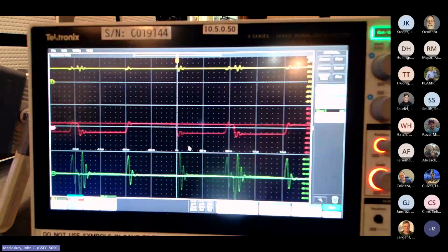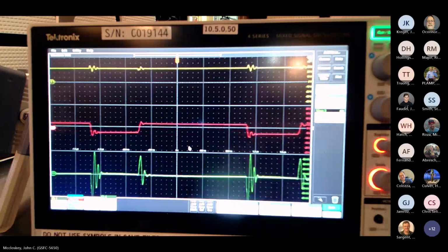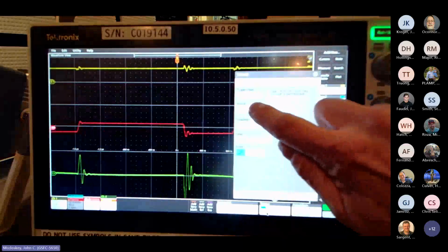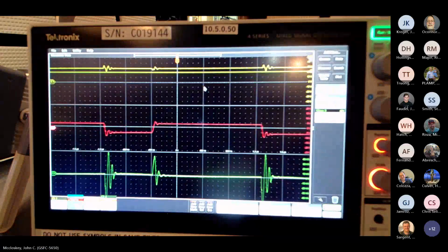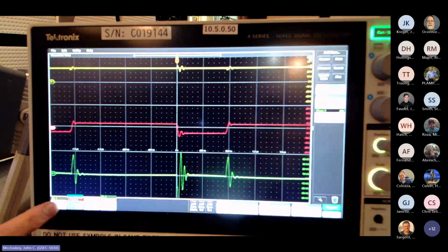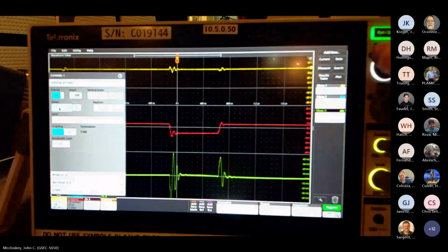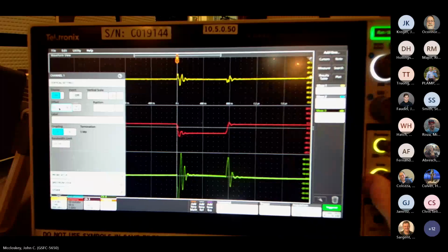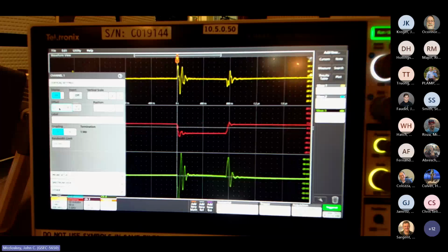All right, first we've got to find our signals of interest. Triggering on a signal that we're not looking at, so that doesn't help. All right, we need an offset on channel 1. There's a lot of noise, but we know that it's a noisy power converter.